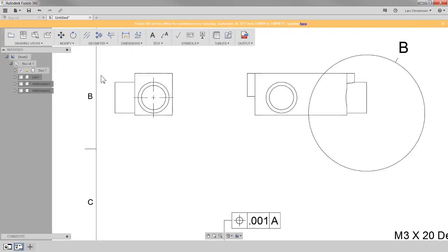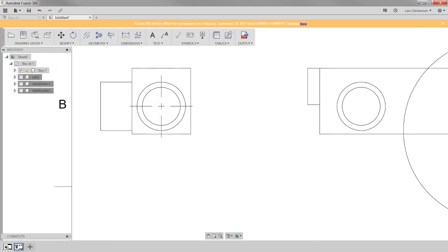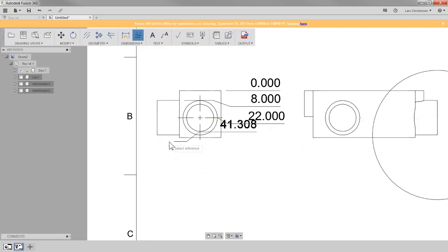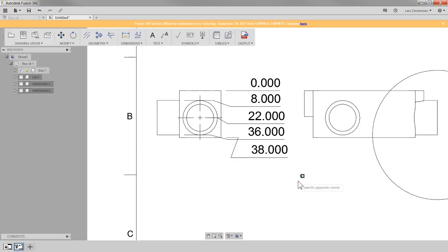Also, maybe this is a good view up here. I'm a big fan, whenever I am doing dimensions or drawings, of using the ordinate dimensions. What that means is if you click on this, you will first place your 0. And then from that point on, I should have placed it on the other side, you can place all the dimensions that come from that 0. You will see how it's adding all these different dimensions in here. You can also select them all.